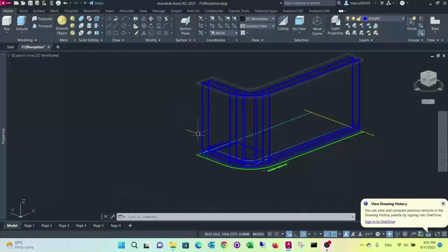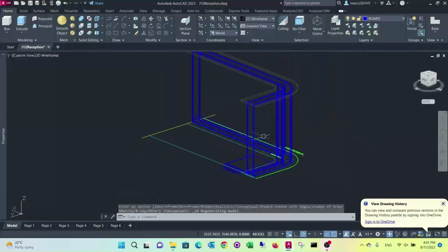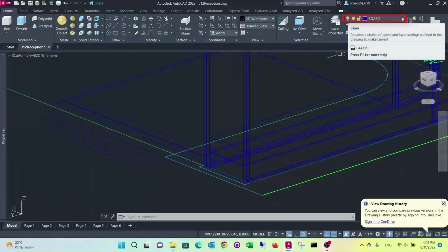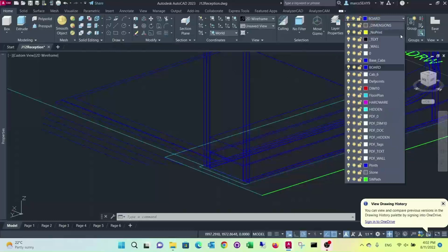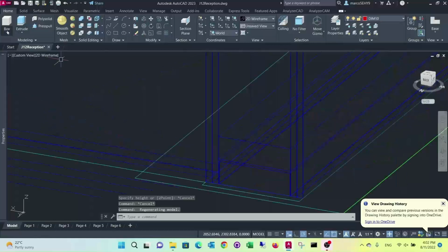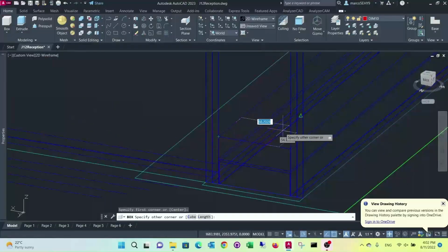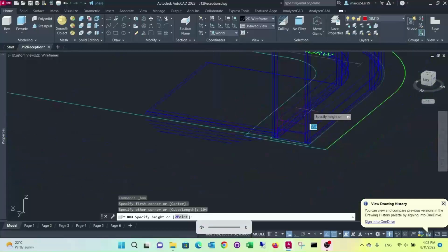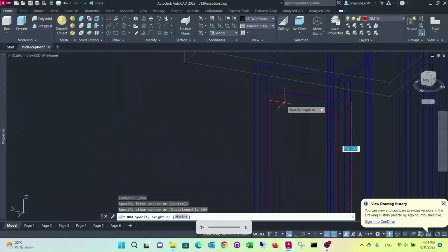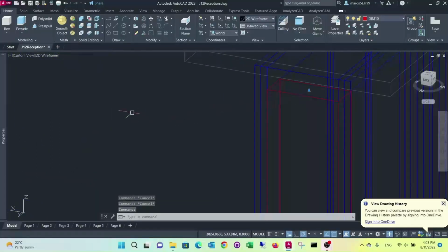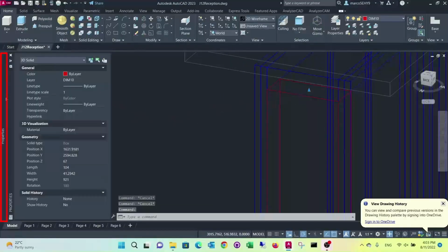The next parts to be drawn are the internal uprights. Instead of using the sweep command, we will use an array path for this. For this part, we will change the layer first so that it is drawn in a different color. This will make it much easier to see. We have to draw one of the uprights first. Now draw the upright. Let's adjust the thickness and then move it back to the correct position.